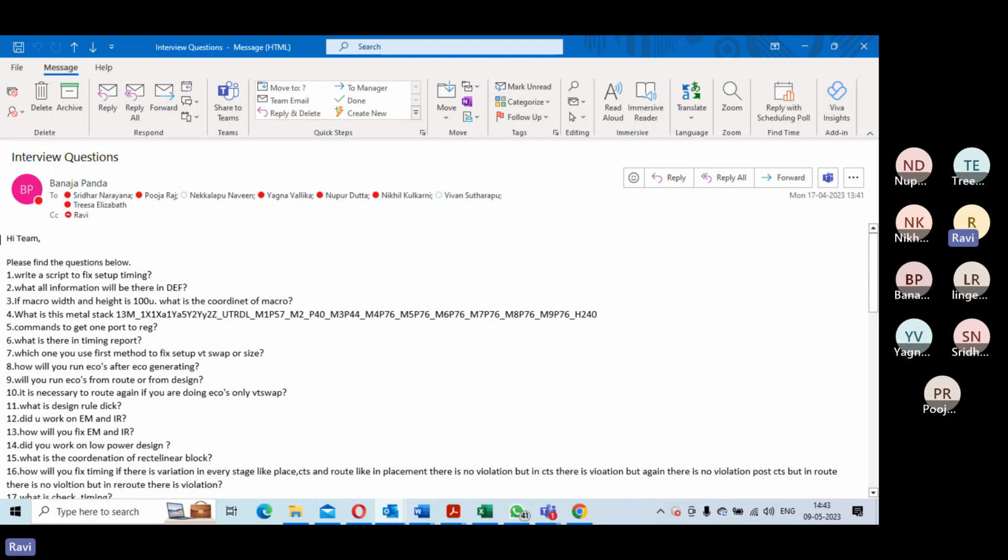Your script, when it is addressing the data path, should first segregate the timing violations in descending order. For example, violations between 1 nanosecond to 500, 500 to 300, 300 to 100, 100 to 50, and 50 to 0 picosecond.